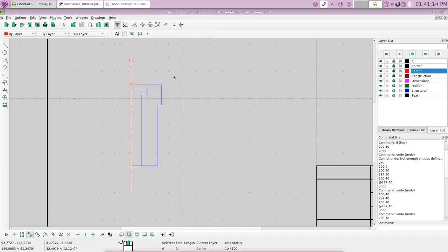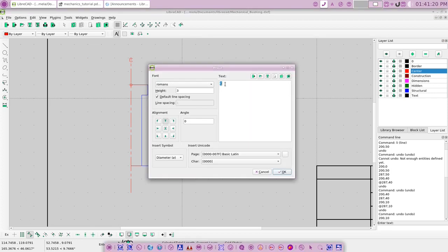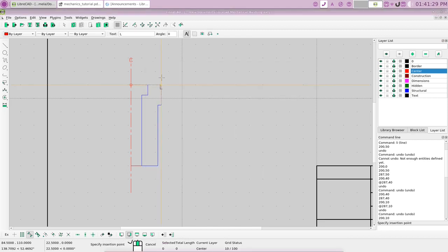Okay, right mouse click once more, and from the menu, choose M text again. Let's put a capital L there. Again 3 for height, that's good. Angle, we don't need an angle. Say okay. Now, that's going to jump up to the end snap again. You don't want that. Take the end snap off and choose free snap. Now you can put the L right where you like it, and we like to have the L just lapping onto the C like that. And that designates that this is a center line. So now the center line is complete, and it's about time to save your drawing.